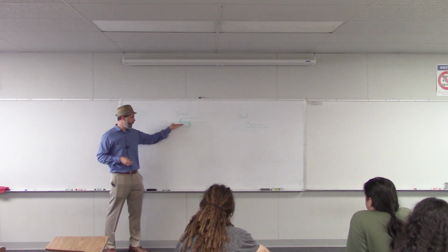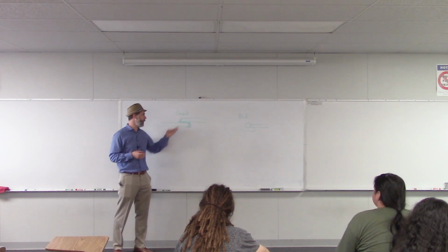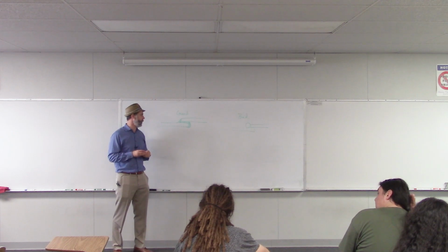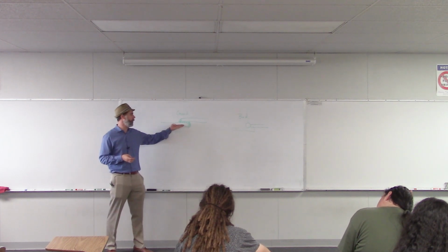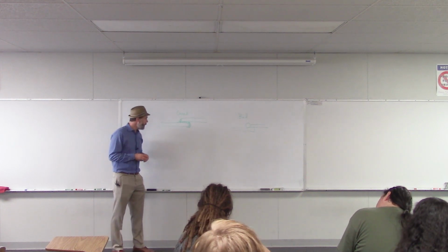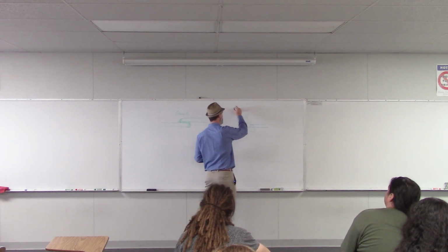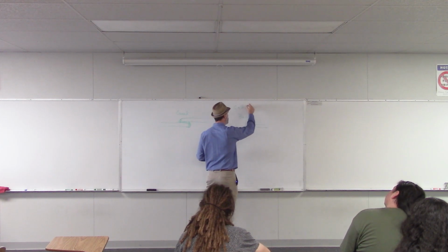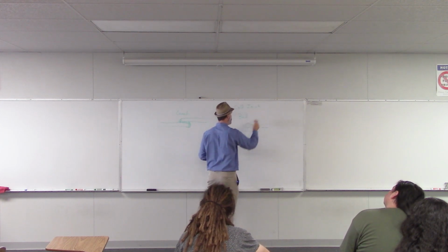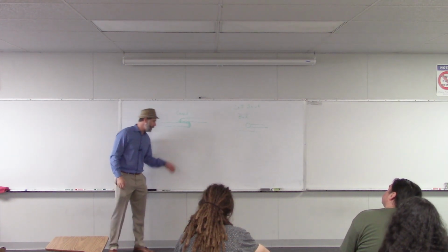This nice, strong bond. And in order for this to happen, you need the metal to be really hot so that the outside of that metal, the components, start to melt and mix with the solder. So that's why we need so much heat. We need the outside of these components to start to melt. This type of joint is called a cold joint because it happens when you don't have enough heat to melt the outside of these components. So we need to ensure that we get enough heat.